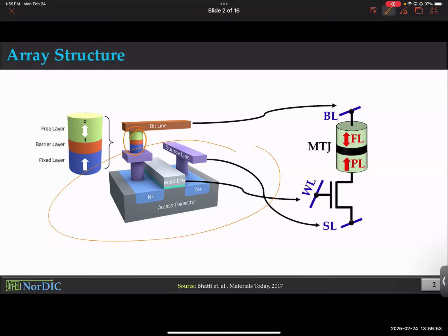But if you come up with a technology which is BEOL compatible, then you can pitch to the bosses or CEOs of these companies that, hey, you don't have to do anything. You just design everything else underneath it. And I will set up a fab for $1 billion maybe, which will only do this extra layer. That's fine. Then hopefully it's win-win for everybody. If it works out, then both of them get to profit. If it doesn't work out, then the big company will not lose, right? I mean, all they care about is basically them surviving, not the other guys. Okay, anyways, now you know, MTJ is BEOL compatible, which is a very big advantage for STT-MRAMs.